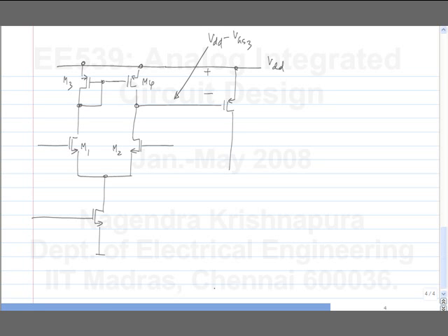What is the VGS of this PMOS transistor? It is VGS 3, right? So this is a case where we don't have to do anything, meaning the previous stage provides the right VGS. So you adjust the size of this, let me call this M11, to give you the correct value of bias current with the input voltage that it has. Whatever quiescent current you decide, we'll later see how much that should be.